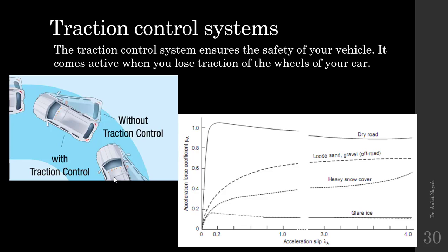system in our vehicle. This traction control system senses the actual real-time velocity of the vehicle, which does not directly correspond to the RPM of your wheel, but to the linear velocity on the ground surface.